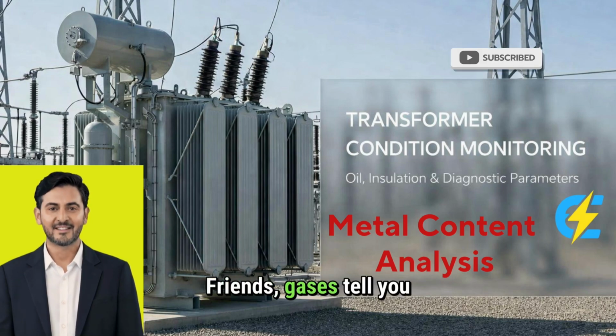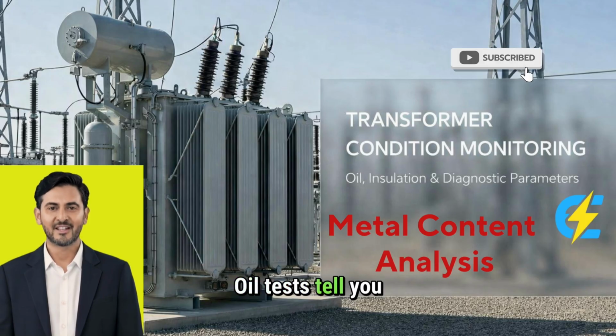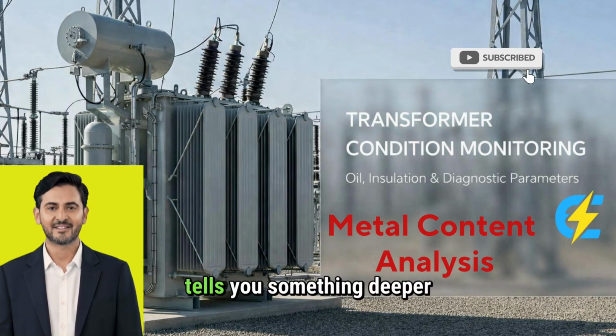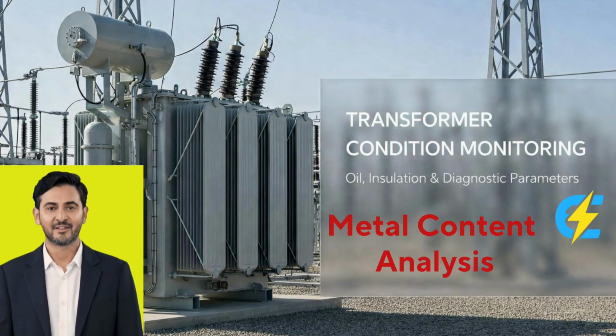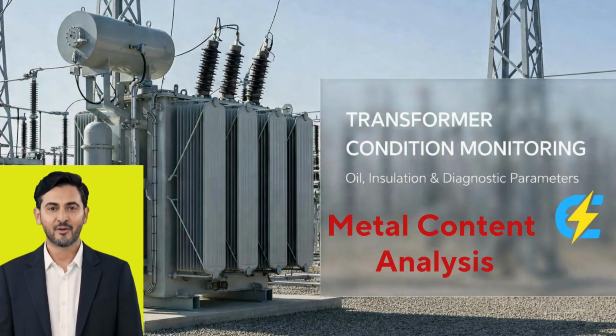Friends, gases tell you what kind of fault is happening. Oil tests tell you how healthy the insulation is. But metal content analysis tells you something deeper. Which internal component is slowly wearing out? Copper, iron, aluminum, zinc. These metals should never be freely circulating in oil.